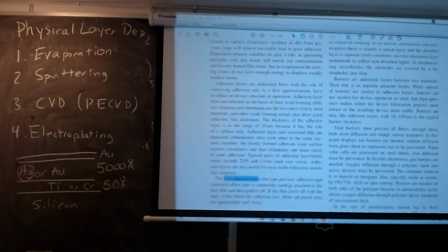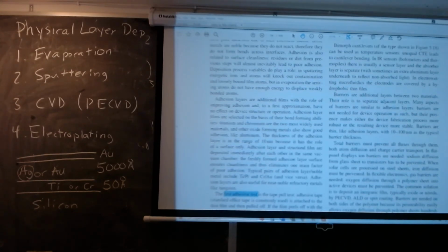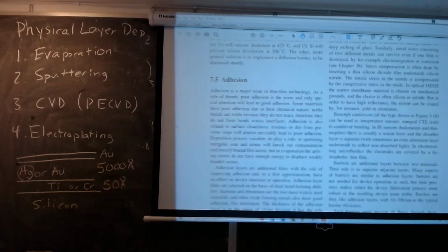And basically, as you develop a recipe, if the contact survives the subsequent process steps, then you're good. So there's kind of no reason to test in the middle of your process. And in fact, if you did put Scotch tape on your semiconductor wafer to do that test, you would have to throw that wafer away because it would be contaminated.